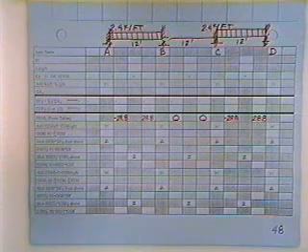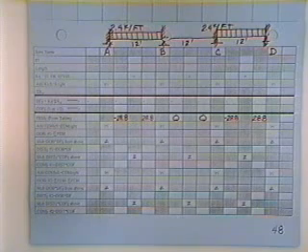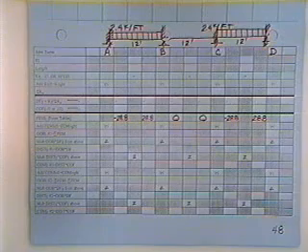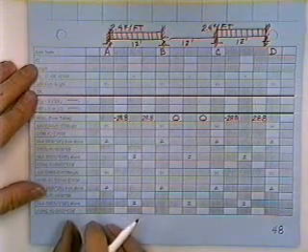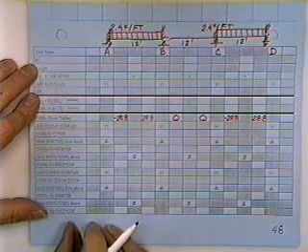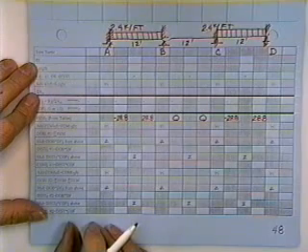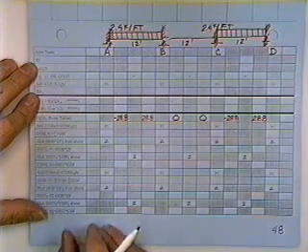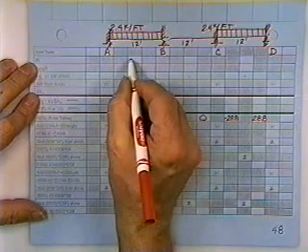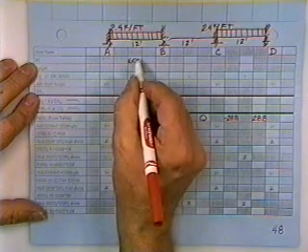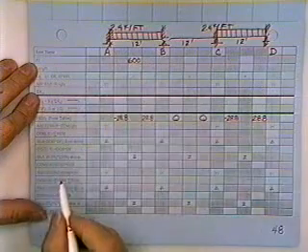What I need to know is how much of the moment released from joint A and released from joint B actually goes into each side of the joint. Now, to do that, at the top of your sheet you'll see some calculations called EI. That's the modulus of elasticity of the beam times its moment of inertia. I picked a beam which has E times I of 600, so you just enter 600 for EI.